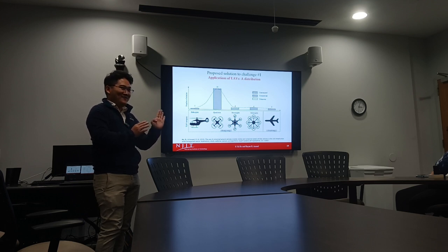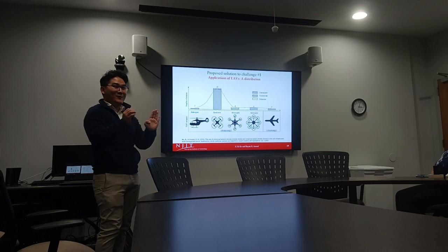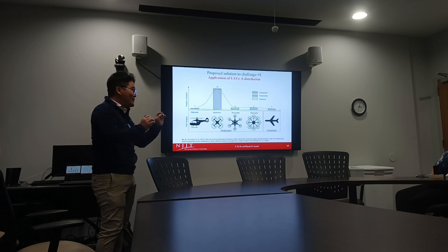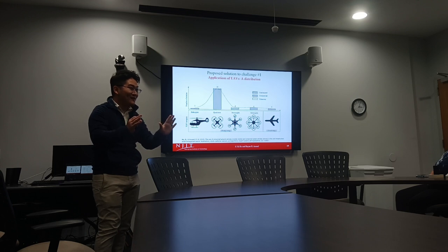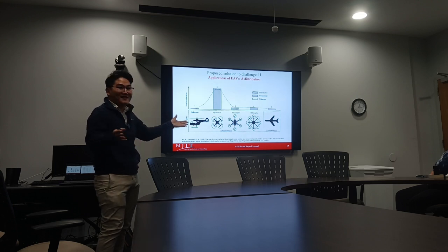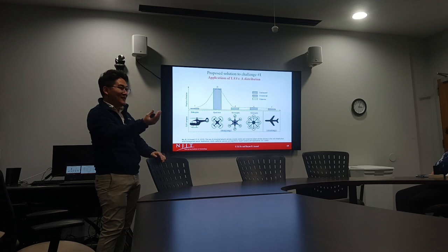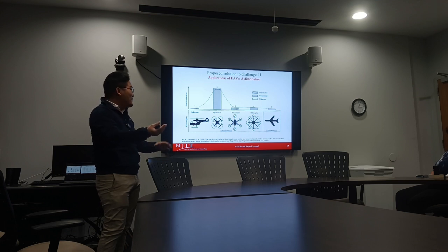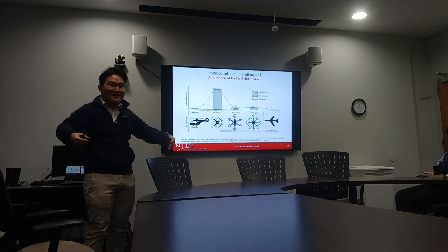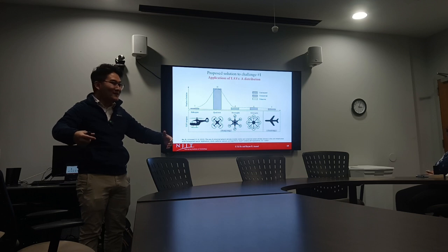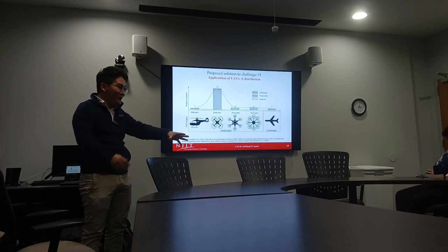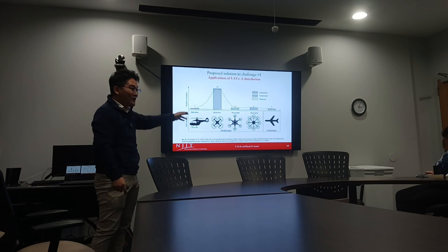Think about the application, right? You need to figure out what we want to use it for. If you only want to use it to take images or videos, a quad rotor is good enough, because the camera is lightweight. But if you want to use it to, let's say, carry a tank of water to cool down the local environment, maybe you're going to need the 8 rotor one.